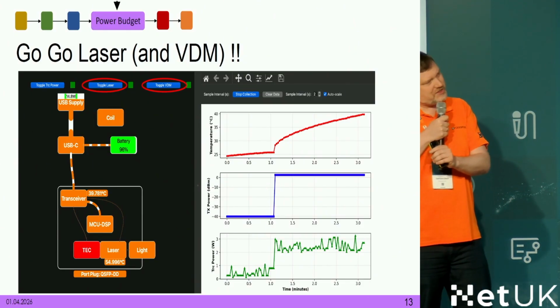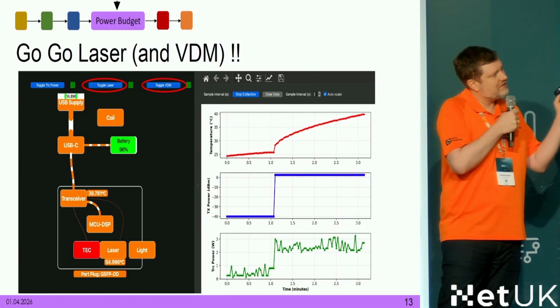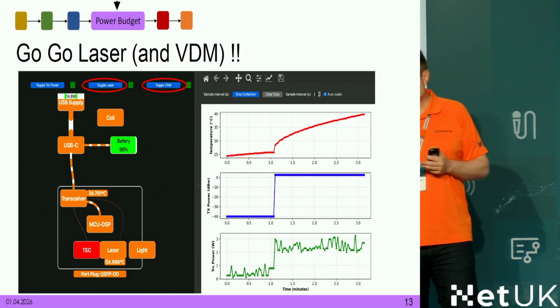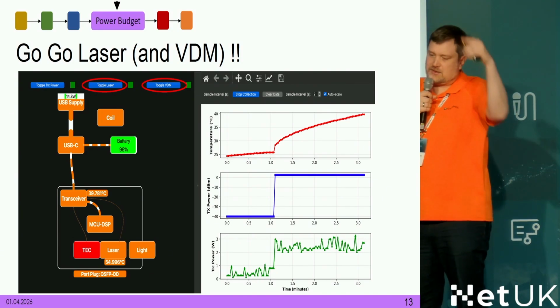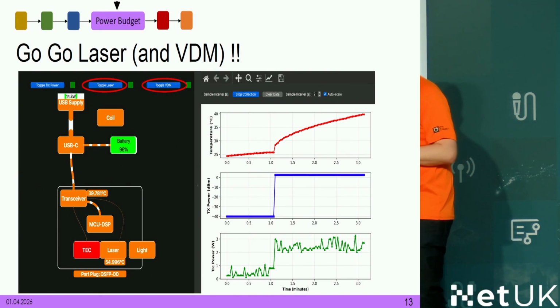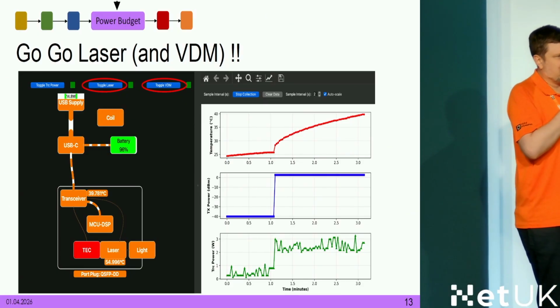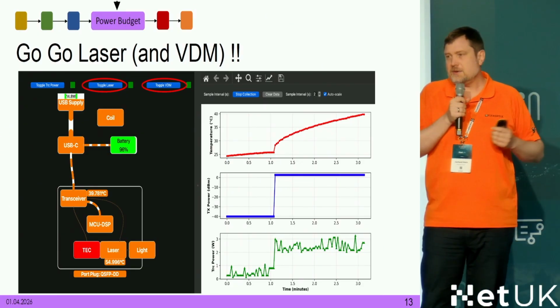This laser temperature is specified at 55. There exist models that are specified at 60. It depends on the laser that is inside. And now we have some signal. It's connected through a jumper cable. You get 2 dBm of power through your line. It was a fiber cable of 2 meters.